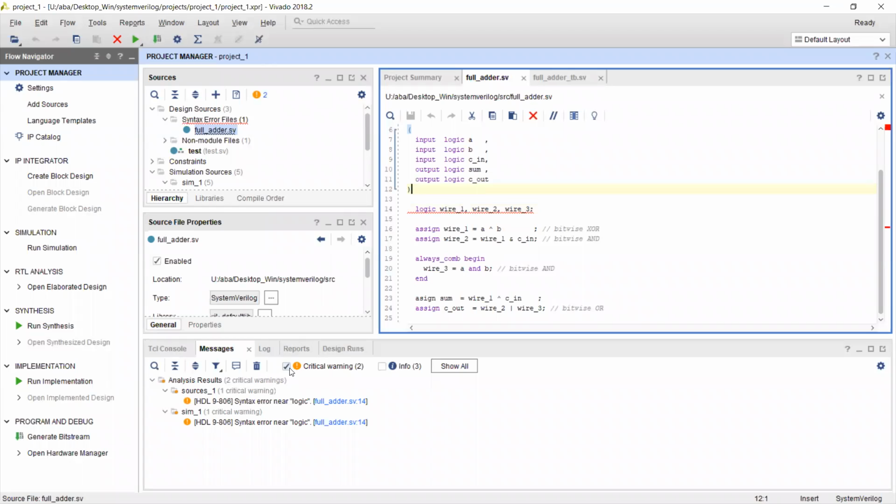So this is a kind of a headache with Verilog as well as Vivado. Sometimes it gives the error in the other line, in the next line. So if it says there's an error in this line, you always look at the line before and the line next as well. Don't look at only that line. So this line is perfect. There's no problem. But in the previous line, we are missing a semicolon. You change that and this error goes out.